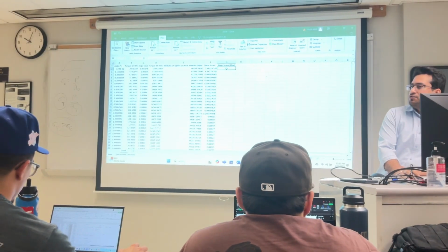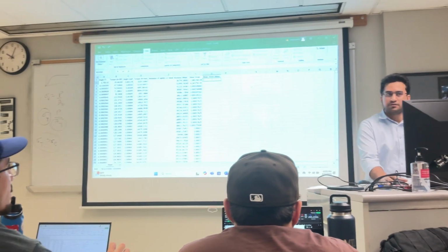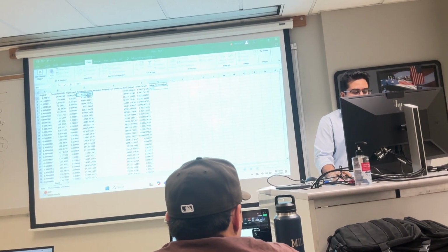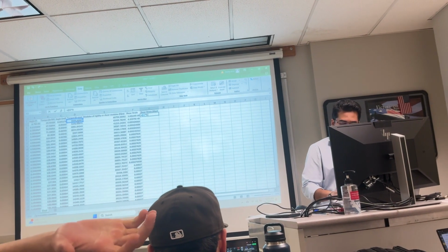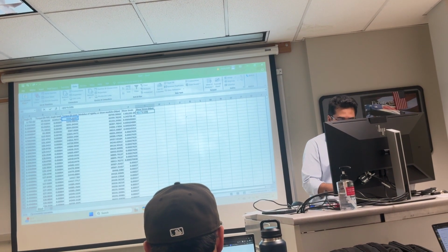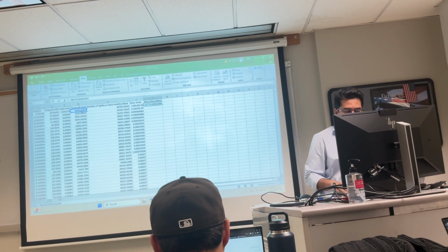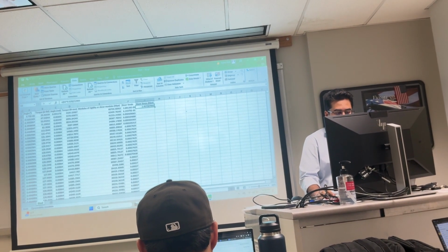I think you want the shear stress. So that one doesn't really need T. 304. T is in newtons. This one is the max stress, multiply by T into R. R is 9.525 divided by J, 12903, right? Okay. So this is my shear stress.